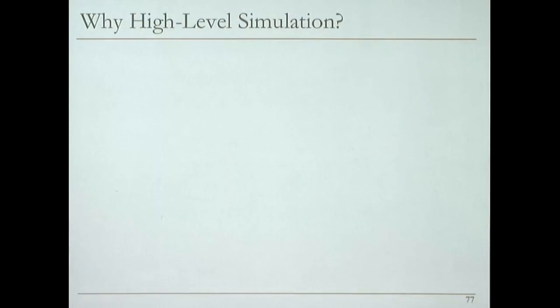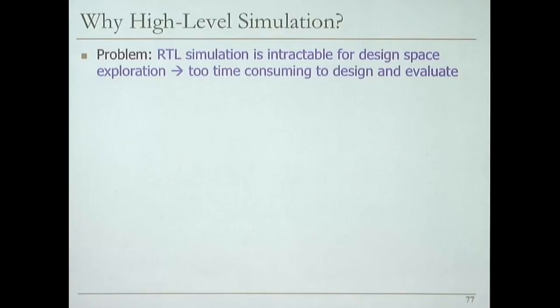So we will do some high-level simulation in this course, but I'll motivate it. For the first lab, you're actually doing low-level simulation. Not at the lowest level that you could possibly do, but you're actually doing RTL design and RTL simulation. But the problem is if you keep doing RTL, not even a real implementation, we're not even considering that at the moment, RTL simulation is intractable for design space exploration. It's too time-consuming to design and evaluate a Verilog design for everything.